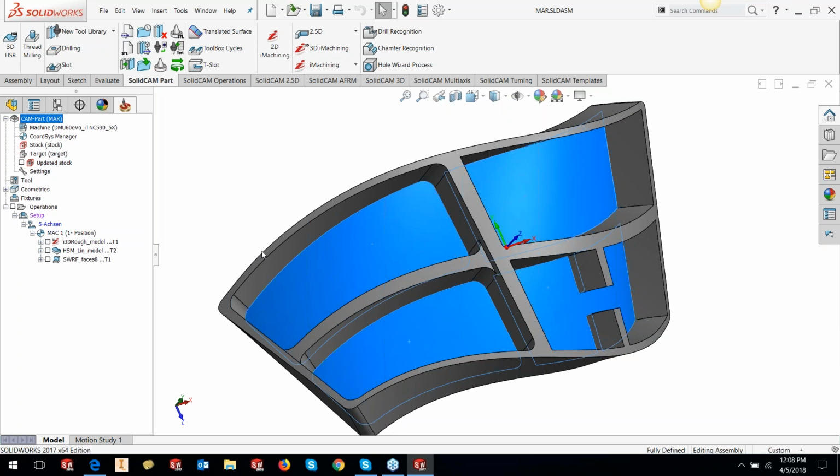It will leave material if the walls are not normal to the floor. So the philosophy is that the tool axis is always normal to the floor surface, irrespective of how your wall surface is. It will always create the wall which is normal to the floor surface.